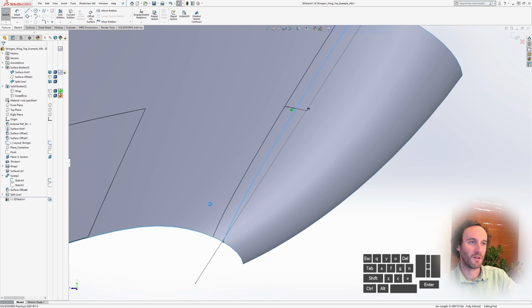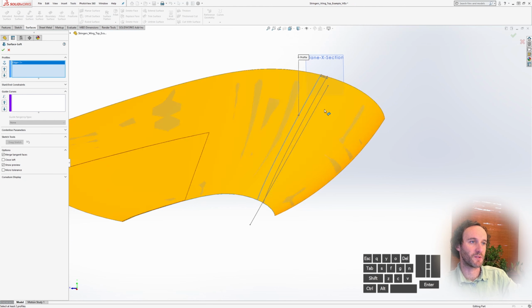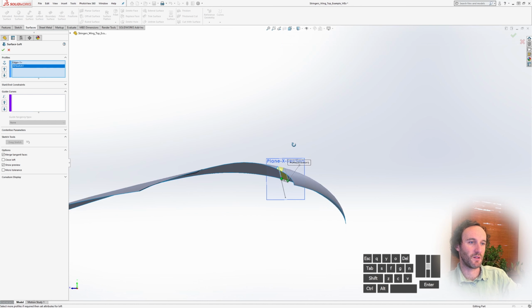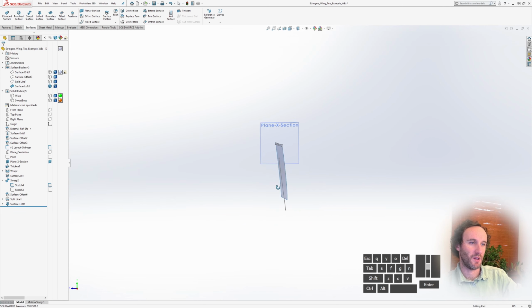And we'll get out of that. And then we can just do a lofted surface. We can even reference that edge and that line that we have there. And as we hide these, that will be a 1/2 inch across the whole way along as it's twisting.